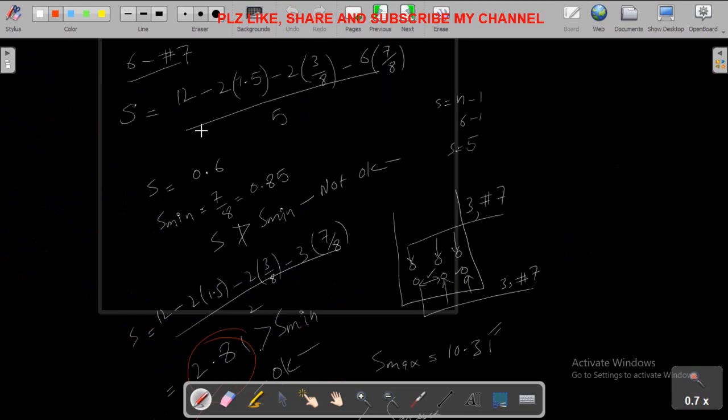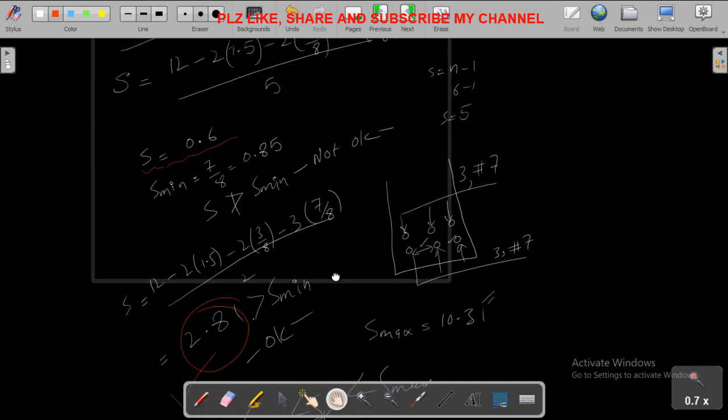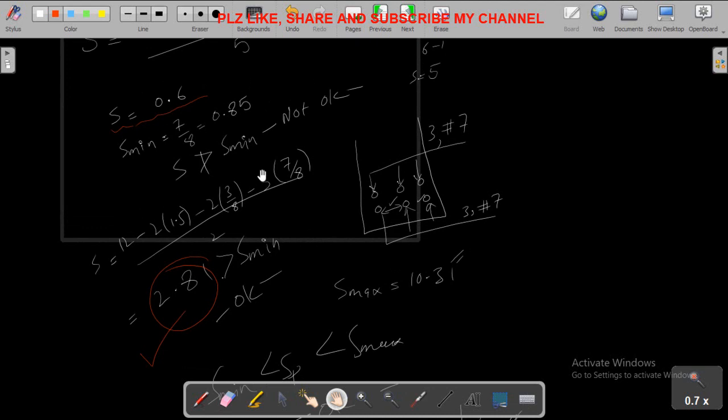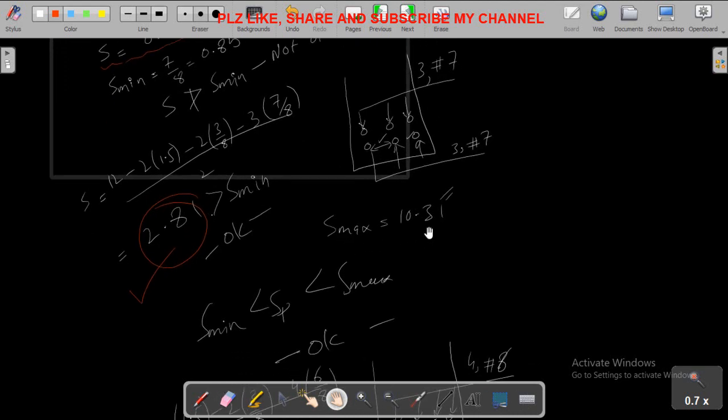Here you can see we calculated S for 6 number 7 bars. The calculated value is 0.6, but in one layer it is not sufficient. So we transfer this calculation to 2 layers, using 3 bars in one layer. In that case S is 2.81, which is more than S minimum, and S max is 10.31.